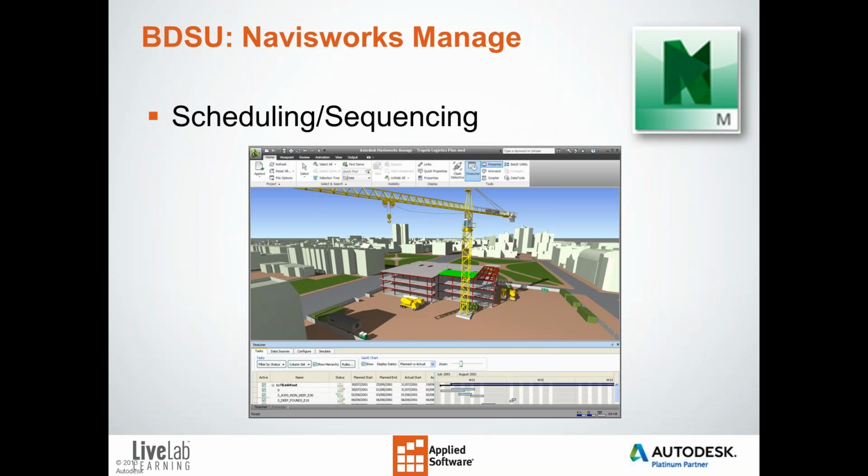Project scheduling. I can simulate construction project scheduling to visualize and communicate project activities and minimize delays and sequencing problems. I can help confirm building or demolition viability by developing construction or demolition sequences that link model geometry to times and dates. I can import times, dates, costs, and other task data from project management software to dynamically link schedules with project models. Then I can set up planned and actual times to visualize deviations from the project schedule.